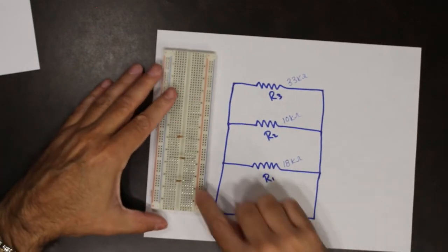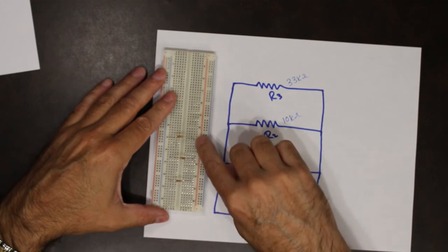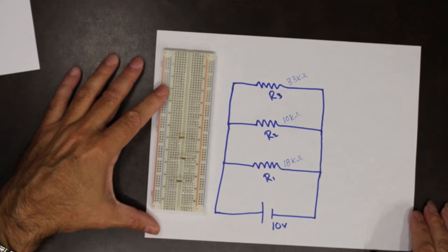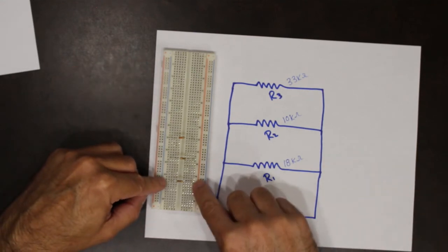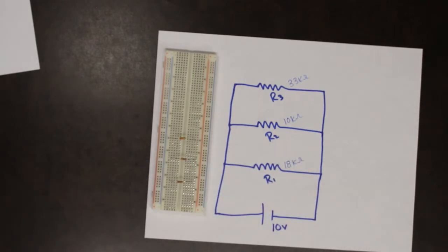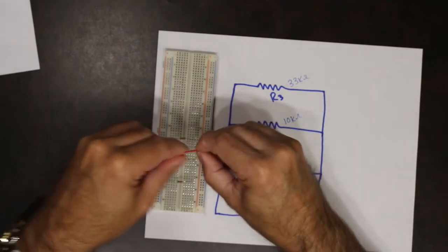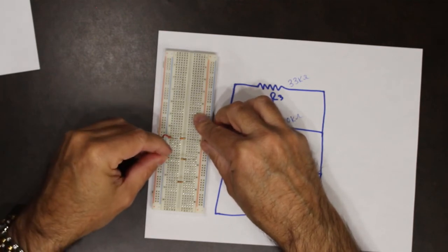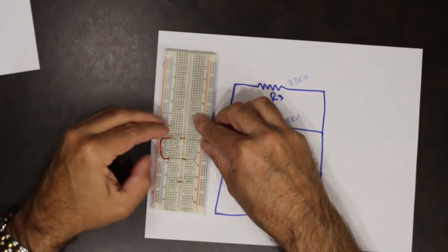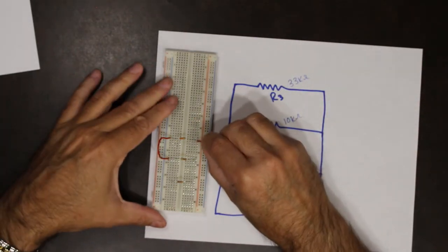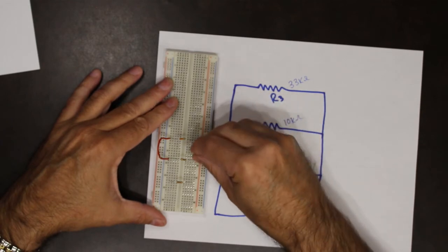So now I have to make the connections, because my board right now, those resistors do not have a parallel connection. There's no connection in my board underneath to go from here to here, here to here to here to here. So I'm just going to do that with some wire. So I have to connect this resistor to this one. I will connect this side to this side.